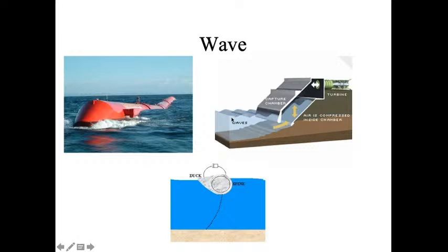What's happening is the waves are powering this wave capture device, which is going to compress air, and that compressed air is going to go through this turbine, which will rotate it in our generator and produce electricity. But it's not super powerful, as we're only compressing air right inside the chamber.